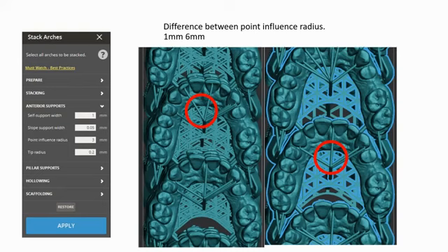You can see on your left side, this is when the parameter was set to 1 for this particular model, and on your right side when the parameter was set to 6 for that model. Of course, if we need support, we cannot magically start printing from nothing. For some tooth positions and inclinations, we do need to start off with a support, but of course you can try to minimize that as much as possible. So those were the most important parameters. There are a few more.